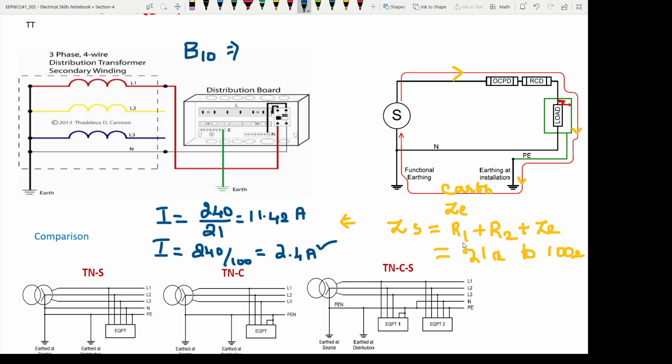So, the reason you understood. Because the loop impedance is a high value, the fault current is very less. Because the fault current is less, you cannot have the MCB opening during the line to earth fault. So, what can I do? How will I protect myself?